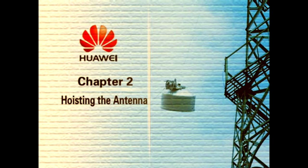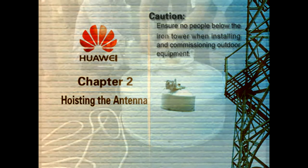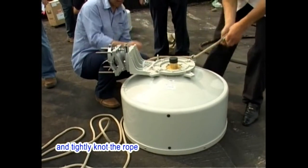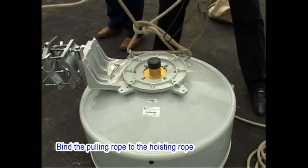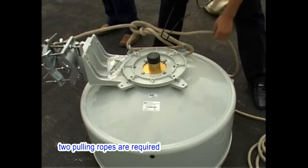Chapter 2. Hoisting the antenna. Caution: ensure no people below the iron tower when installing and commissioning outdoor equipment. Thread the hoisting rope through the hoist rings on the antenna and tightly knot the rope. Bind the pulling rope to the hoisting rope. For a large-size antenna, 2 pulling ropes are required.